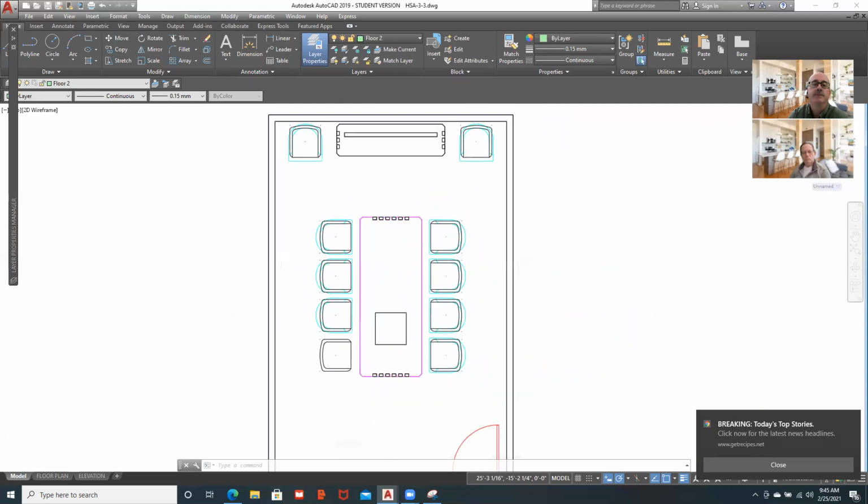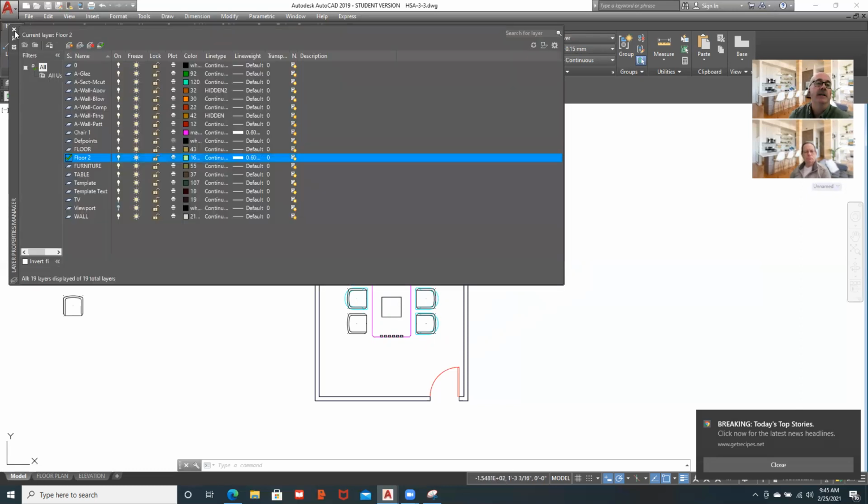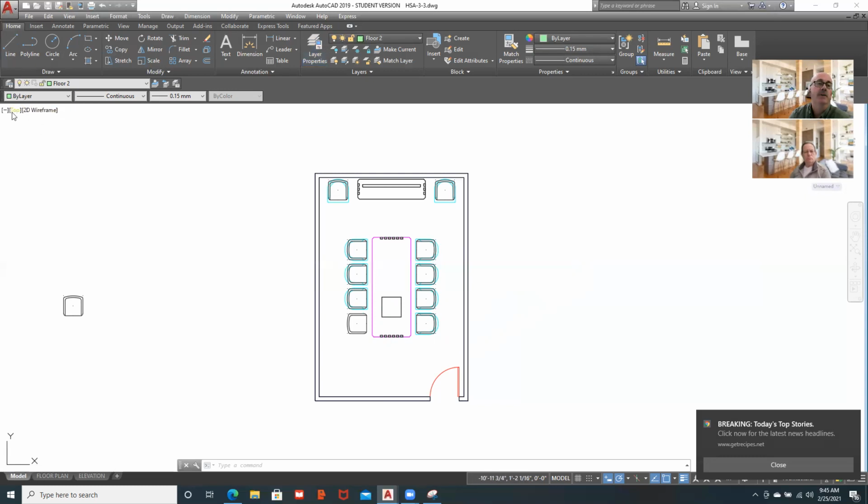What do you think, Al? Well, you've got to make sure that the wall is not total height, because if you put in the height, it's going to catch the top versus the bottom, and you want it in the bottom portion of the wall. So what he's talking about is the Z height, or the elevation of the drawing. And you can't see any elevations when you're in a top view.